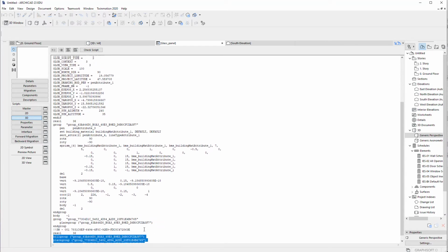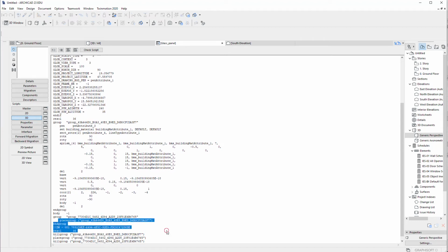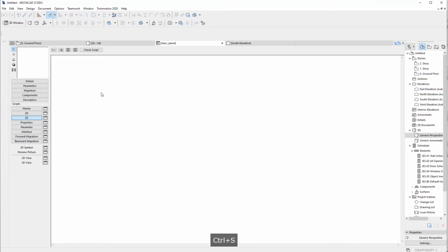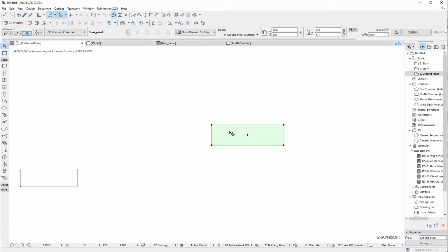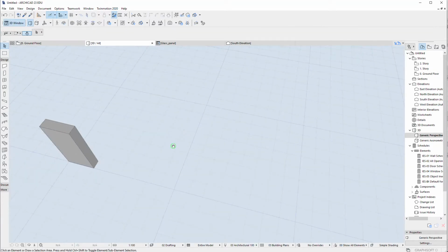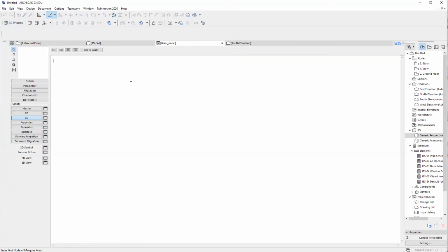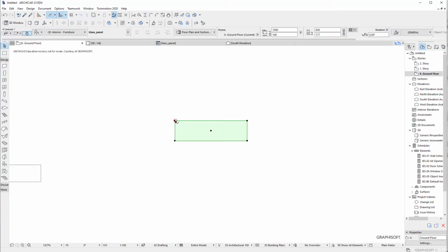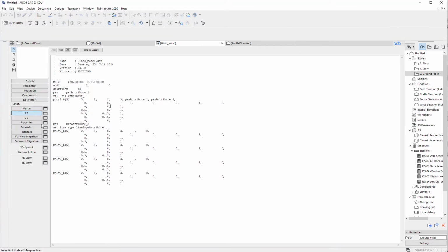So what we will do, there's also grouping the object, but we don't need all of this. We can now remove it all, and now if I save it and go to the object, you see we have the 2D view, but in 3D we have nothing. It disappeared because there is no 3D script running, but the 2D script is still running. So we see here that 2D and 3D are disconnected from each other. The 2D script is doing the same. It's drawing a poly using those points. The bin attribute, everything here is based on a poly point that's disconnected from the 3D, but it's based on the A and B.